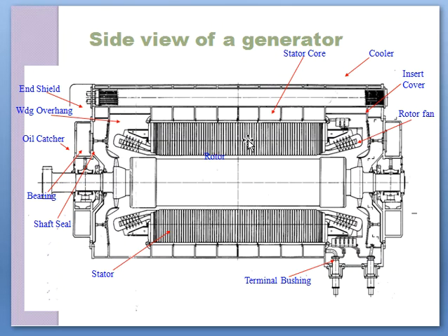Now the windings are coil shaped. So the sides of the coil are the conductors and the ends of the coil are called the overhang portion of the coil. One side of the coil is inserted from one slot, comes back through another slot to the same side and connected here. So these are the stator winding.